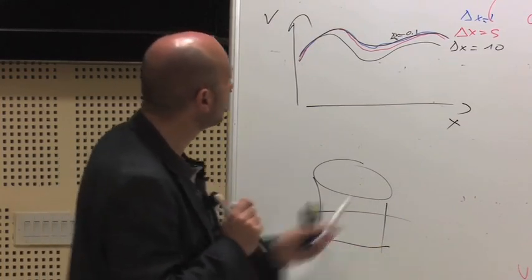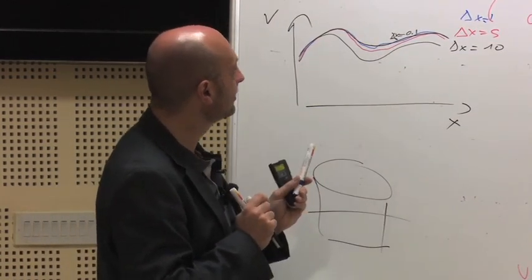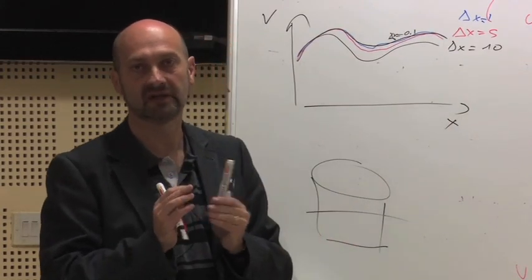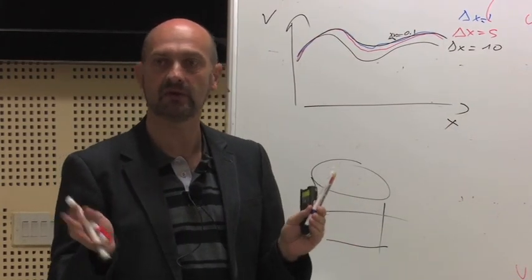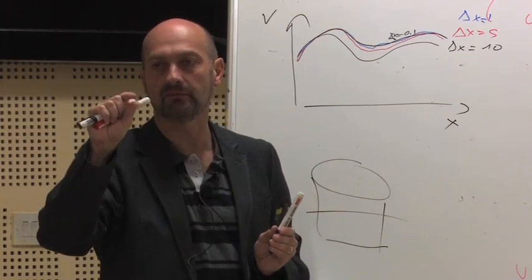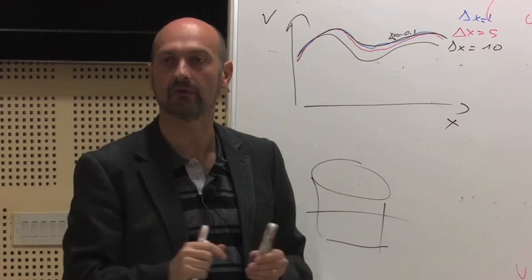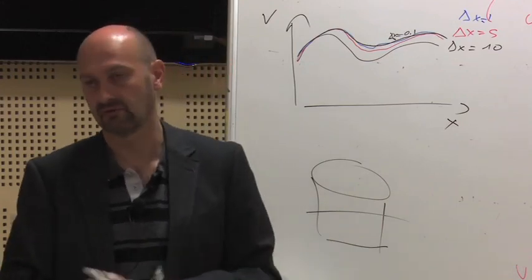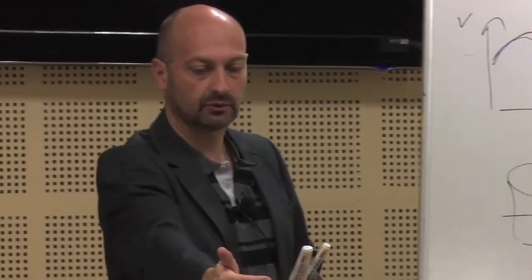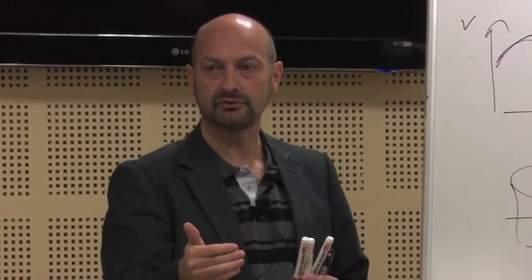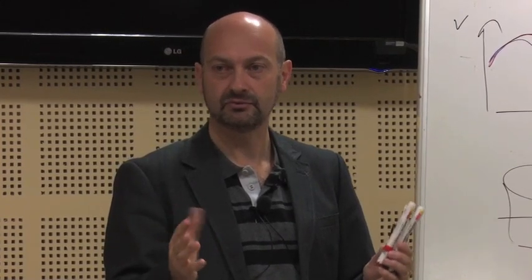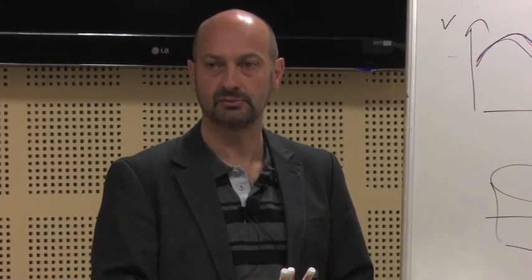So you are going to say, okay, 0.1 is converged, but finally delta x equal 2 is not so far. That's enough for me, and I'm saving time, and I'm running all my simulations with delta x equal 2, and I know that I have, let's say, 5% error based on that. So this is usually what you do. You go further in grid convergence, and then you go backward to select a mesh which is coarse enough to have acceptable CPU demand.